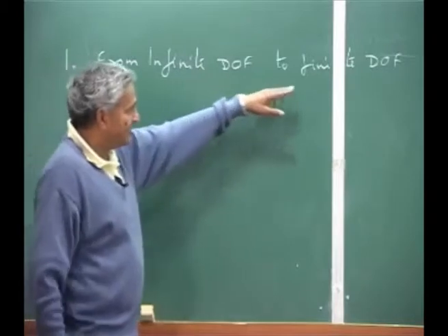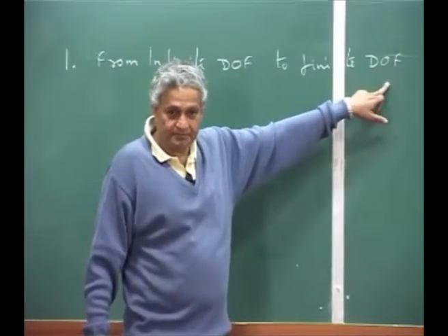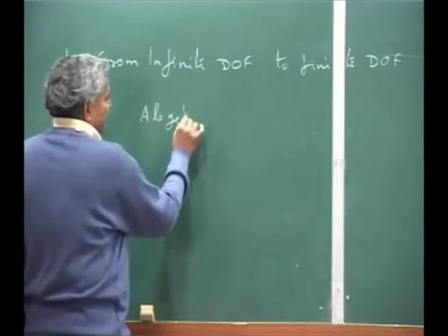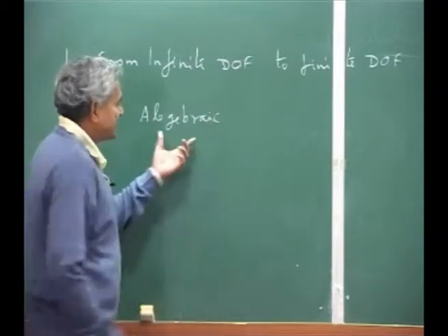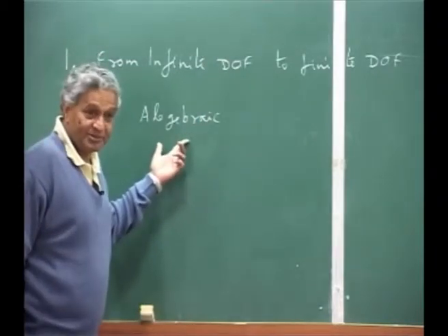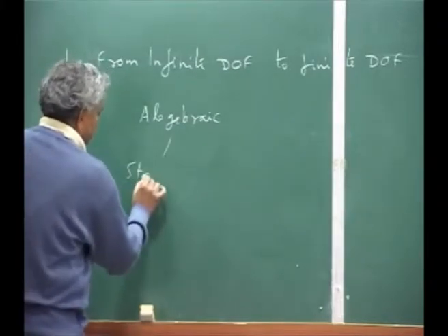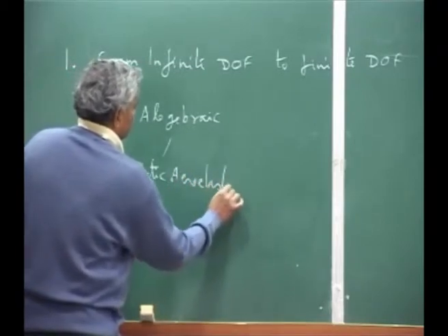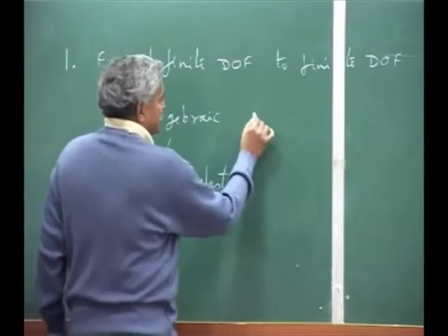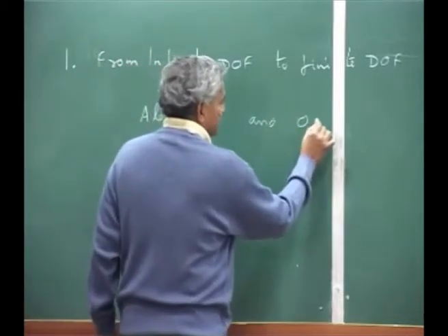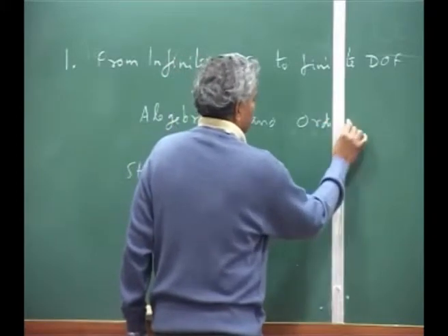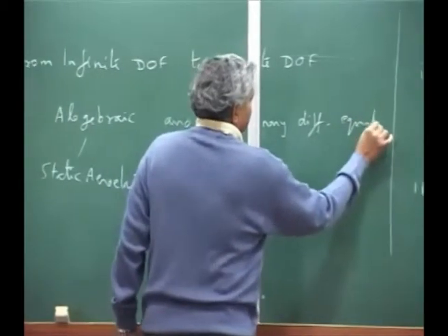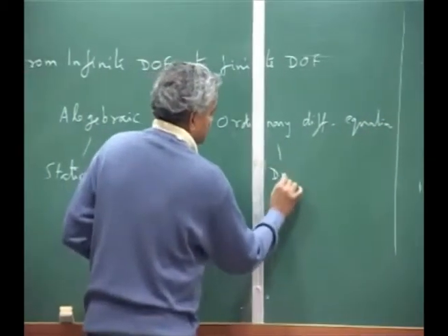So when I convert to a finite degree of freedom system, the equations can be algebraic in static aeroelastic problems, and they will be ordinary differential equations in the case of dynamic aeroelasticity.